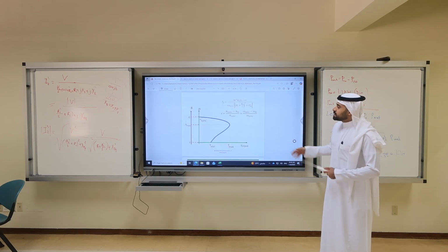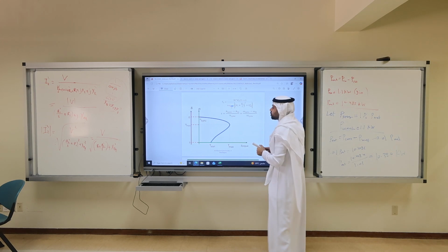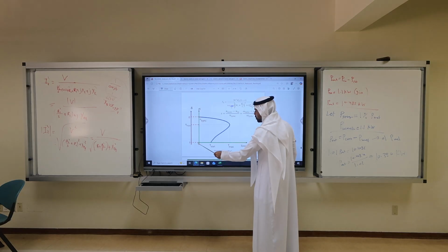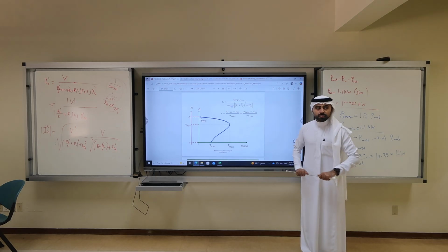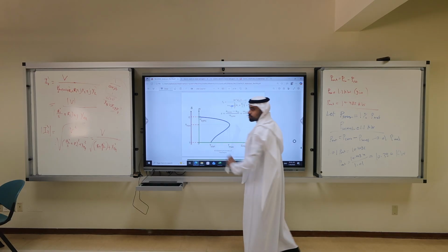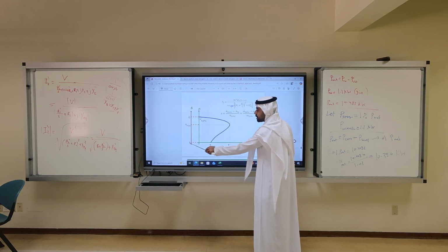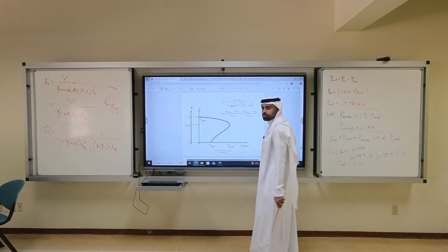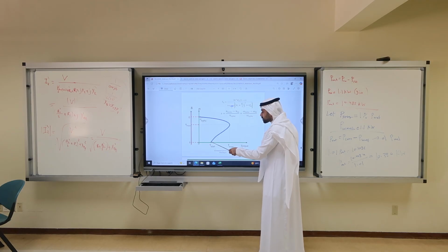So, you take this, how to fix this? So, you plot the speed from 0 all the way to sync. This is sync here. Correspond to it slip from 1 to 0. Why 1? Because if we start, speed is 0, slip is sync over sync, 1. If I reach all the way to sync, slip is 0. So where is my start? My start here, at a torque we call the starting torque.